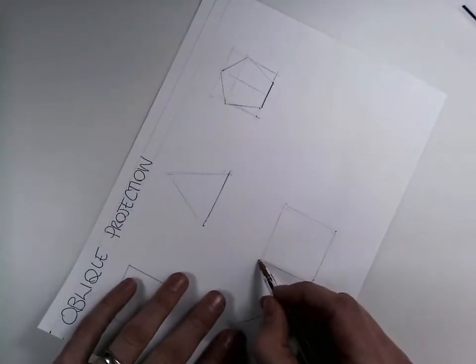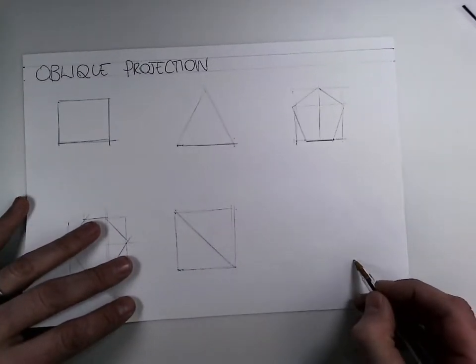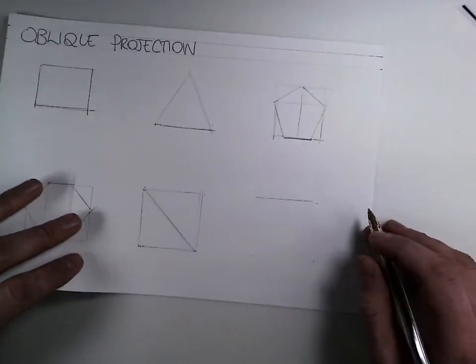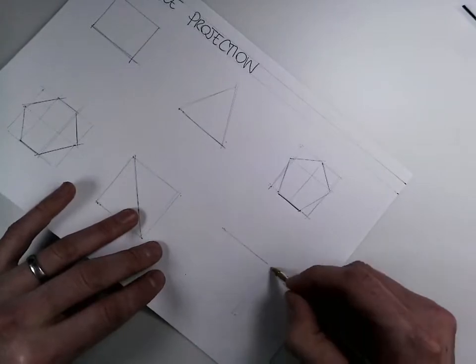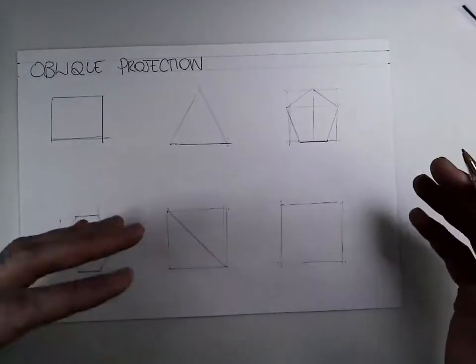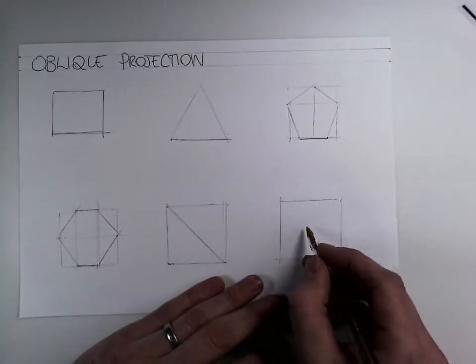So let's go for a right angle triangle. Nice and easy. And the one I always get asked about is how do you sketch a cylinder? Whether we're doing oblique projection, a perspective view, or isometric later on, it's all the same sort of principle with the crating technique. So you take your square, divide that up,